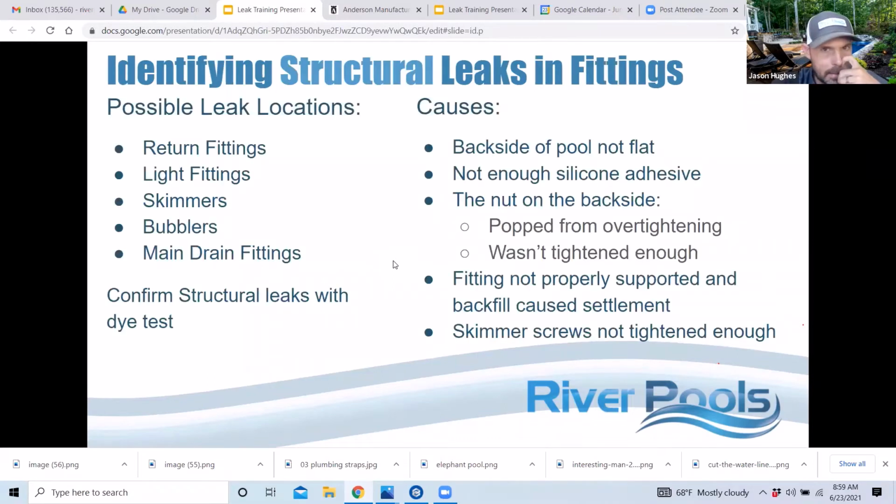All right, so back to Frank's question about the light conduit. What's going on there, Frank, and chime in if you need. When we run our light conduit, because it's a flooded conduit, it fills with water, and that water is going to try to equalize with the water level in the pool. So if our junction box is lower than the water level in the pool, that would probably be the issue. You might just need to raise that junction box up above water level, and that would fix the problem.